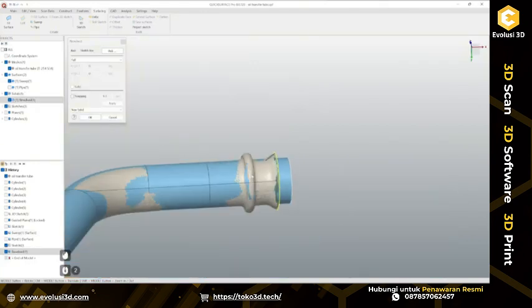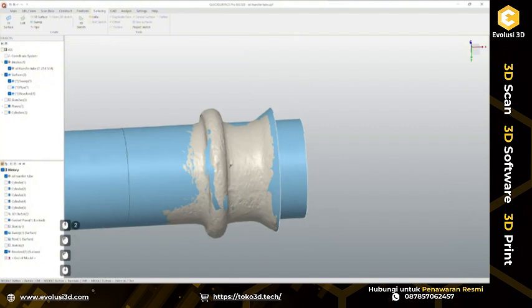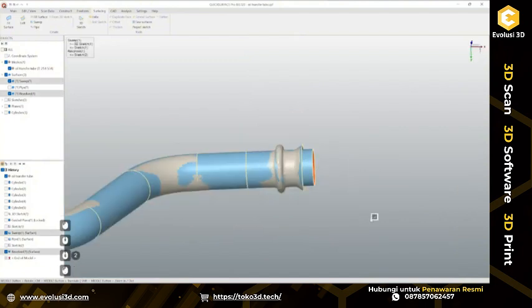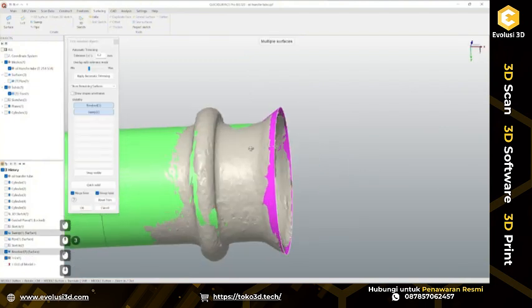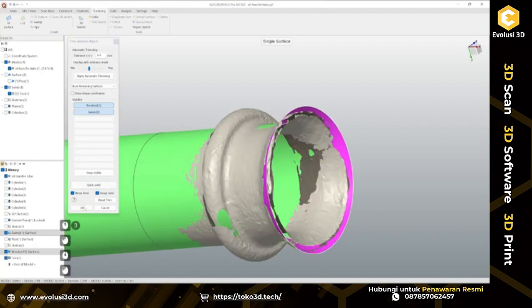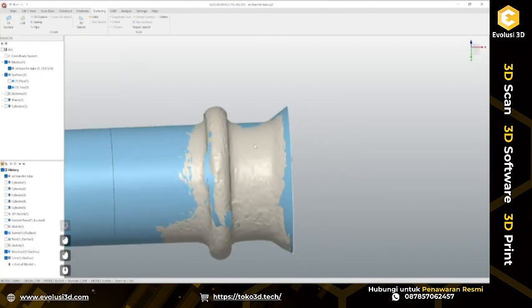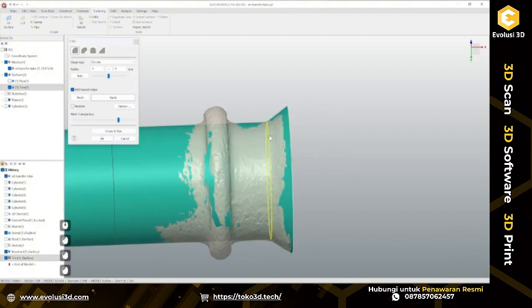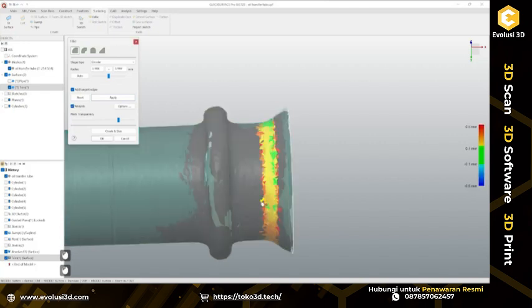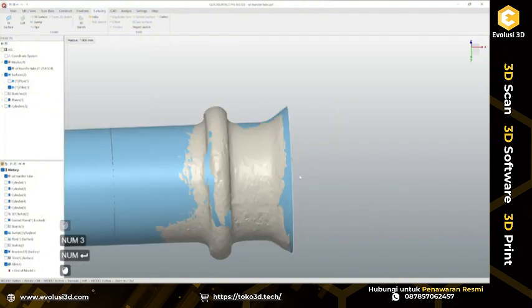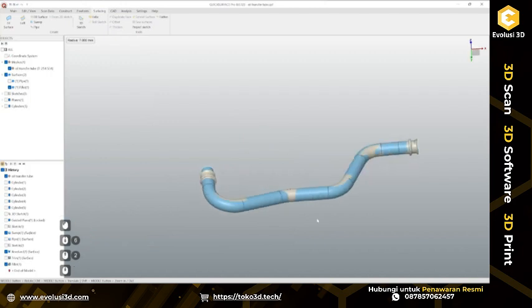Okay, now I can create revolve here. Good. At the same moment, I can trim it, both sides. Okay, nice. And add here a small fillet to match the design intent of this part. Okay, so one side is done.